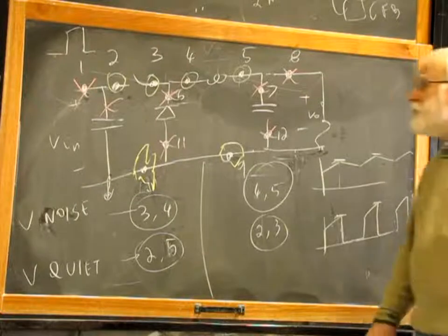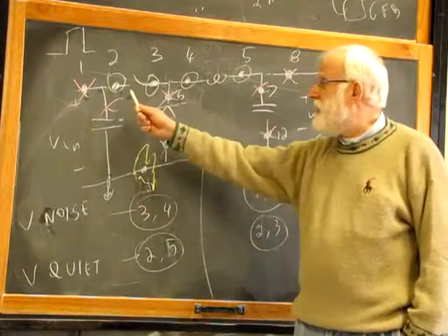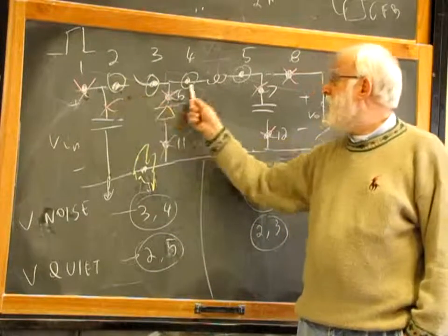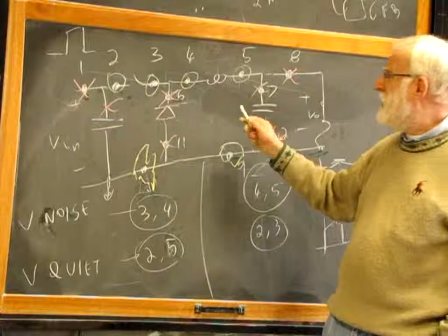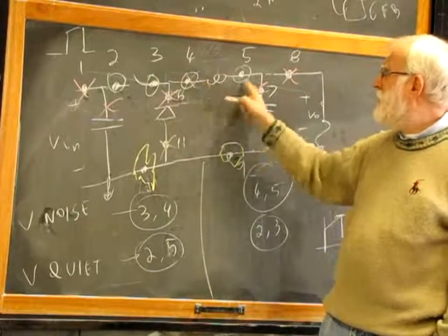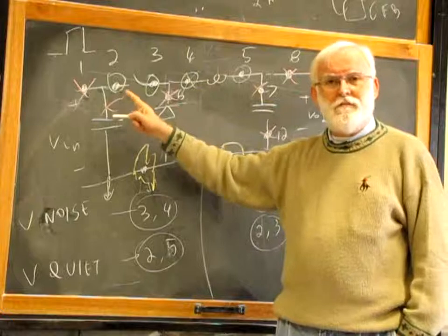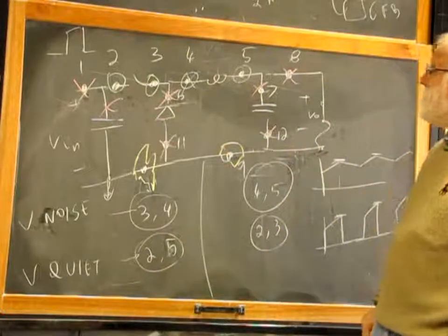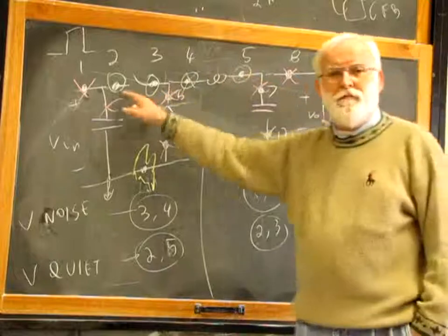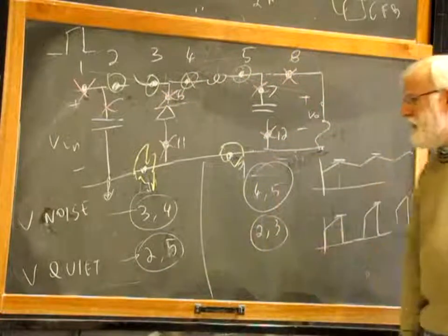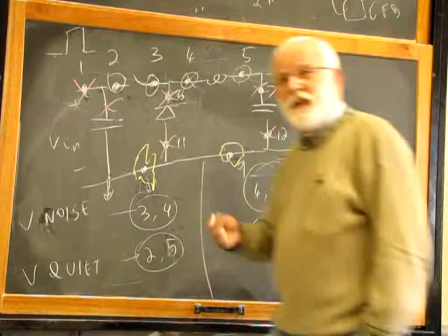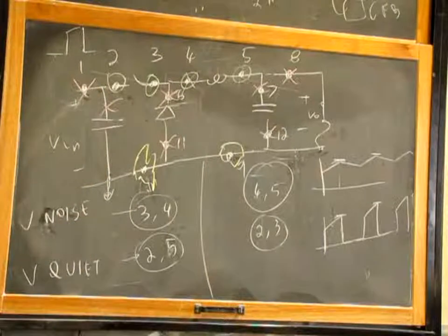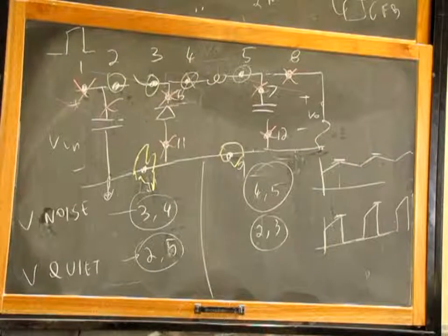So in general, we are going to sense the inductor current either here, here, here, or here. All 4 of them are used. Probably only the number 4 is not used. 5 is used, 3 is used, 2 is used. I stay in any case with 5 and 2 because there is less noise. But let's see, which one do we pick? Because we have 4 possible candidates, and which one to pick depends on what technique you use to sense a current.